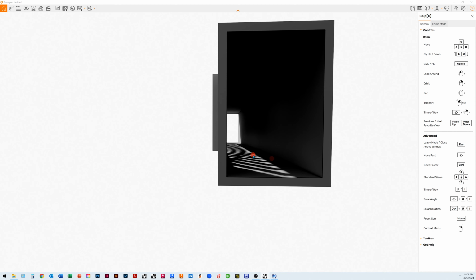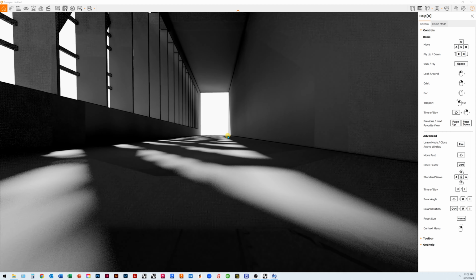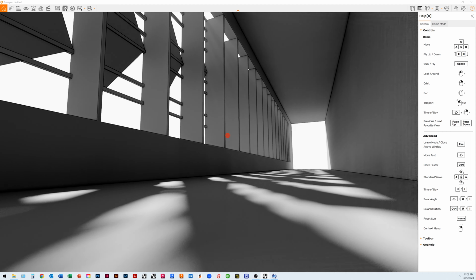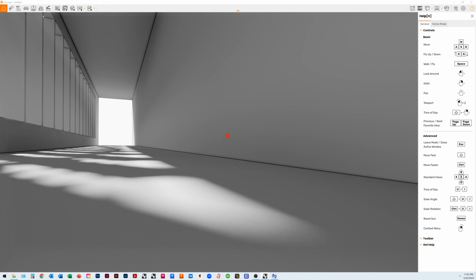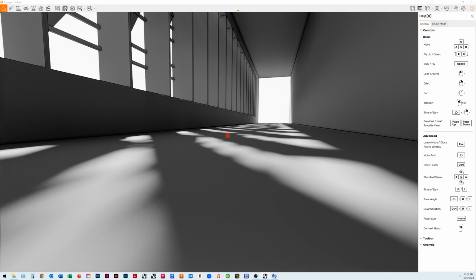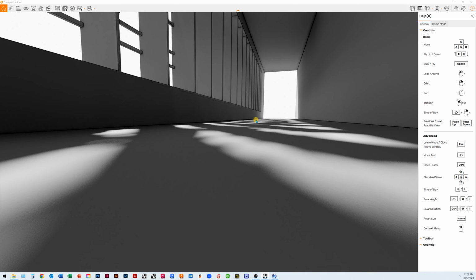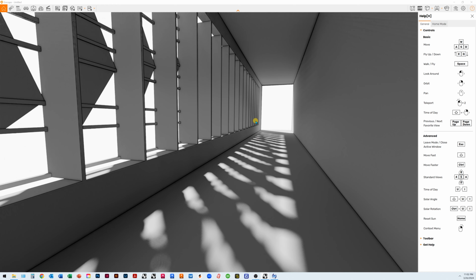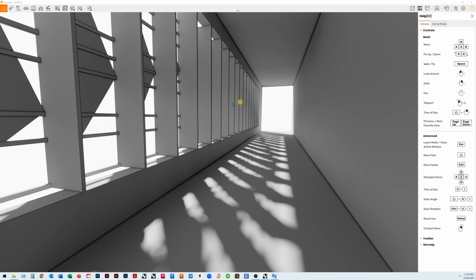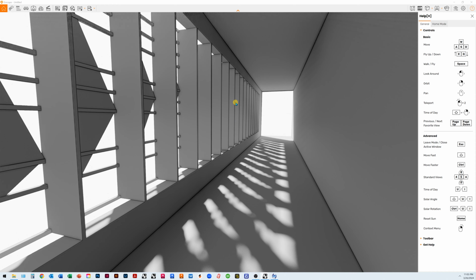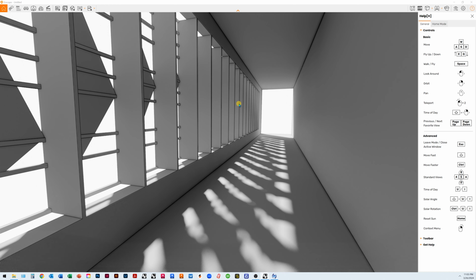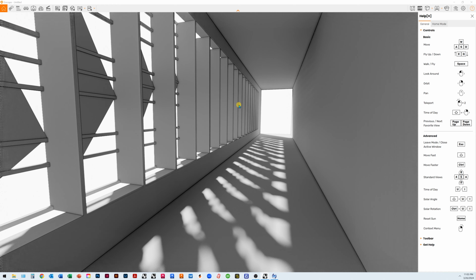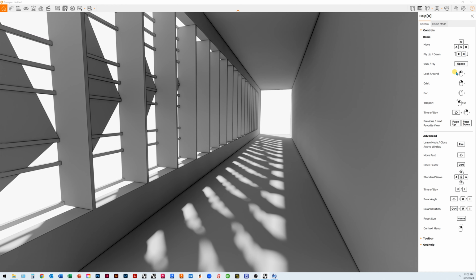Right? So I'm primarily left clicking and then holding the left button down and rotating around. That allows me to look around. And then you can see once you're inside a space, you can move yourself forward and backward, left and right, and then up and down with the keyboard, that WASD-EQ. So if I want my eye level to shift up or down, if I want to slide to the left, slide to the right, forward, backward, I'm using all of these keys to do that.